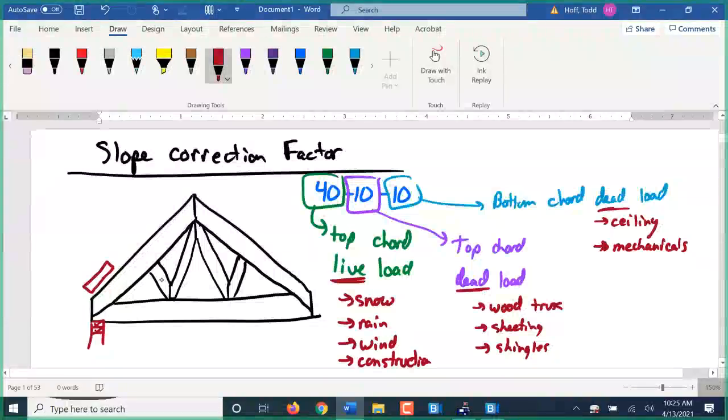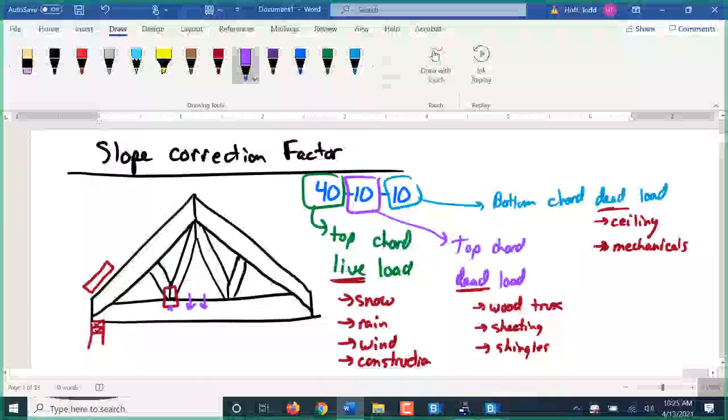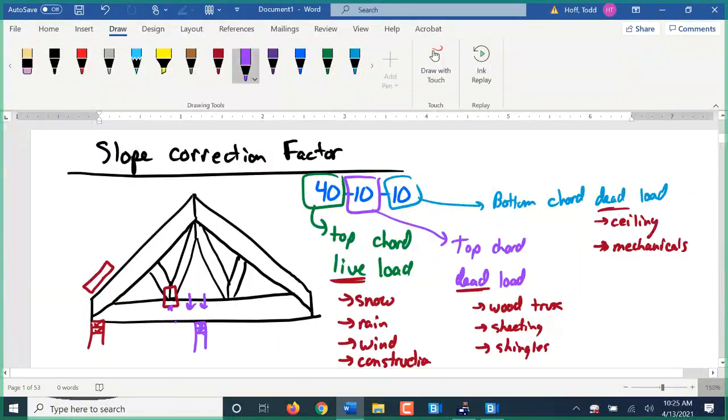These plates here that hold these webs on will start to separate because the extra load pushing down here will pull those plates out. Also, the fact those things vibrate quite a bit when they're running, it loosens up those plates. So you really want to do it in a section where there's some sort of a support wall or a closet or something underneath here that's going to help support some of that weight.